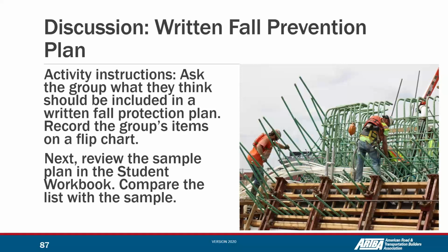We usually have to do the hazard analysis and identify all the fall hazards that we have and all the categories of fall hazards, because not all the fall hazards are the same. Sometimes we are working at a high altitude. We have to consider falling from equipment. We can also consider falling from the same level. We have to consider also the impalement risk. For example, these guys are working very near some rebars. If they fall, they can be impaled by these rebars.